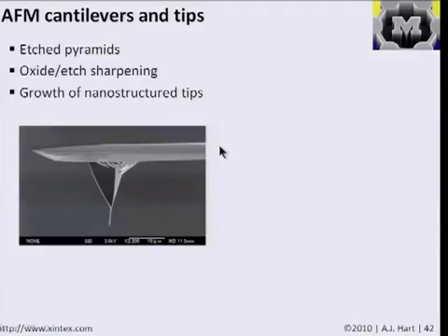So as you can imagine, to get images with such high resolution, the design and fabrication of the tips is very important, because it is the shape and the characteristics of the tip that determine the type of picture you can take. At one limit, imagine you're an AFM: if you're taking an image with your fist, you're not going to have nearly as high a resolution as if you're taking the image with your pinky finger. And if you have, for example, a groove in your sample that's this big, my fist is not going to fit in, but my pinky finger is going to fit in.